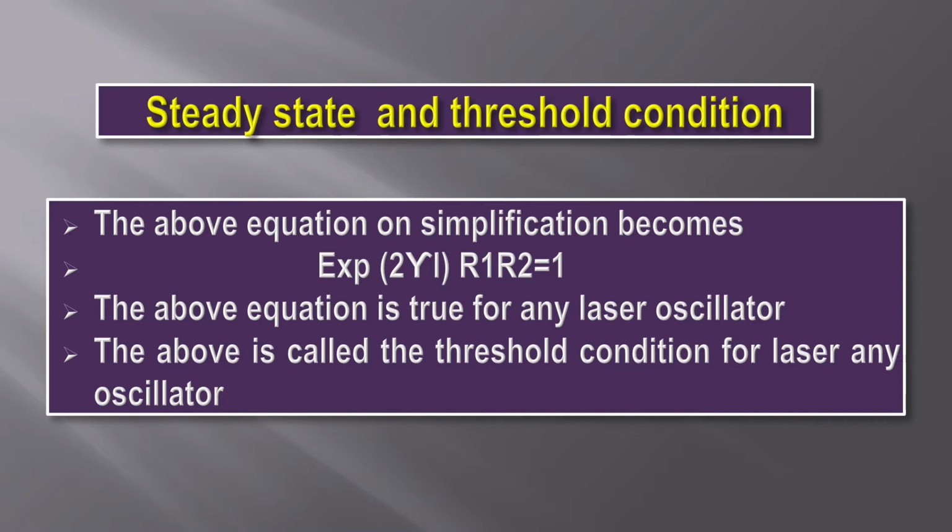Remember, even if I switch on and work with the laser for 3 hours, 6 hours, I would be able to get the same 5 milliwatt from morning to evening. This is the steady state condition, or the minimum threshold condition. Both are equal for a CW laser. This story is different for a pulse laser, which we shall see later. The most important point here is the coefficient gamma, which is called the gain coefficient. This is something like a profit in a business. Let us see.